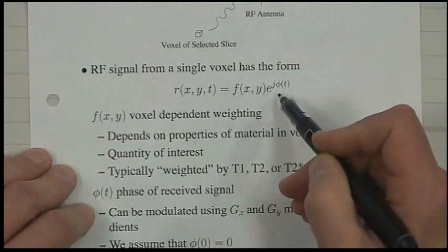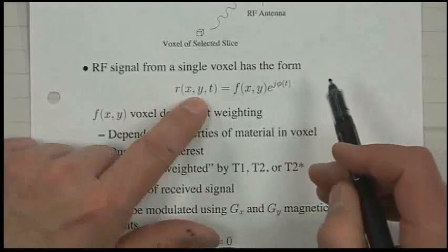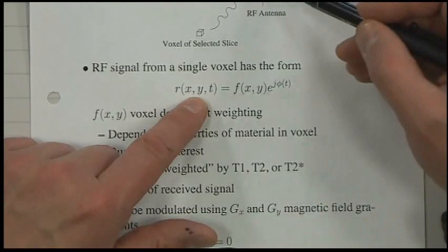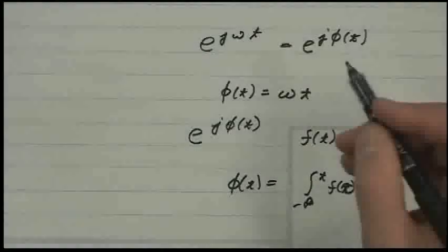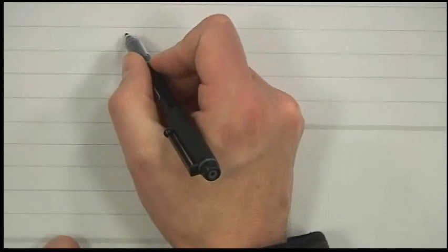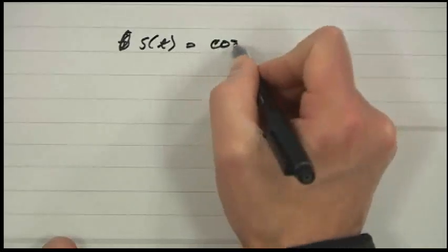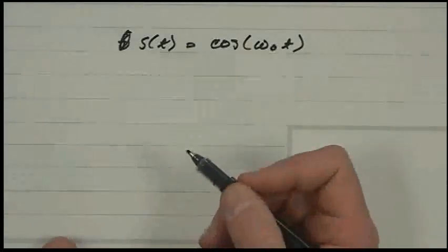Is this because of shifting frequency? Well, no, it's just that this received signal is a modulated signal, right? I mean, nominally it's coming in at 63 megahertz. So it's not going to be just a constant that's real valued. The way you represent it in communications, if you have a signal, say S of t, equal to cosine of omega 0 t, is typically in complex notation.